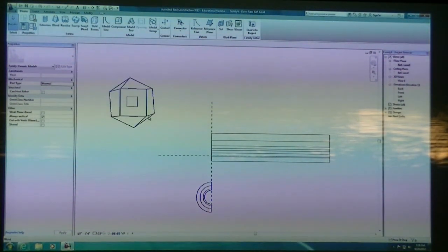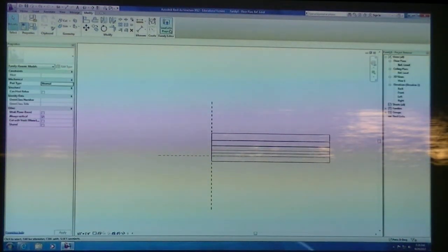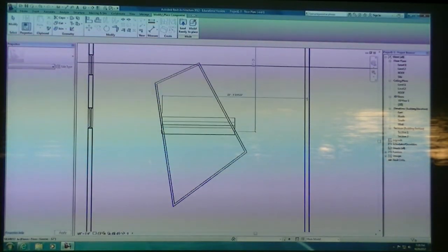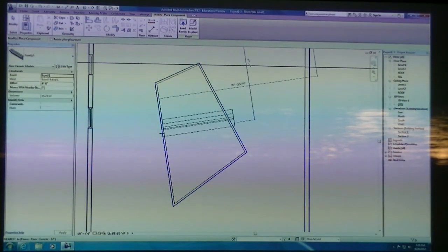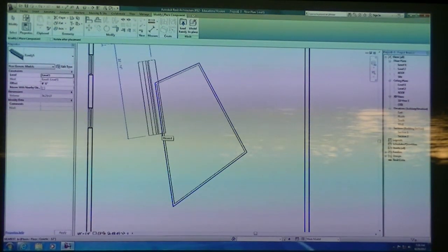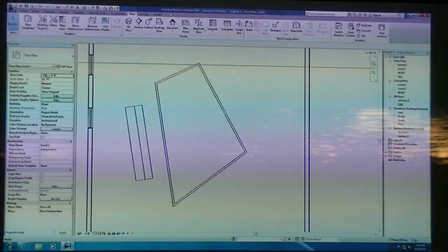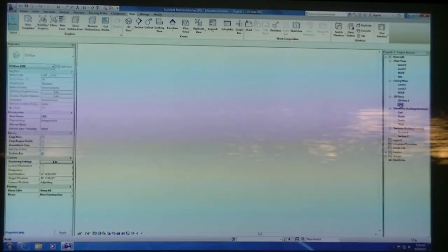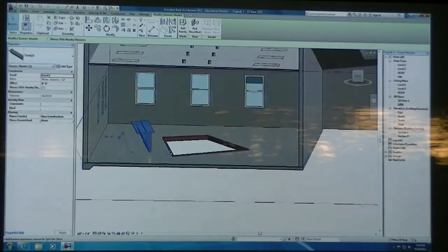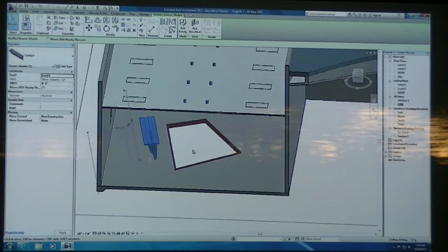So I've got all these crazy shapes here, but if I just keep my desk that I made and load that into the project, you're placing it just like a component where you can hover over an angle and hit the space bar, and it aligns with that particular angle, and you can place this on level 1 and the different floors. And so when I look at my space here, I've got my bar that's right next to the slab edge here.